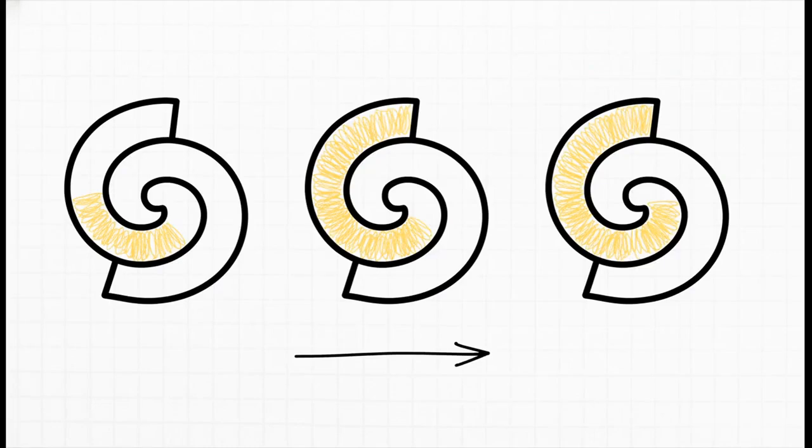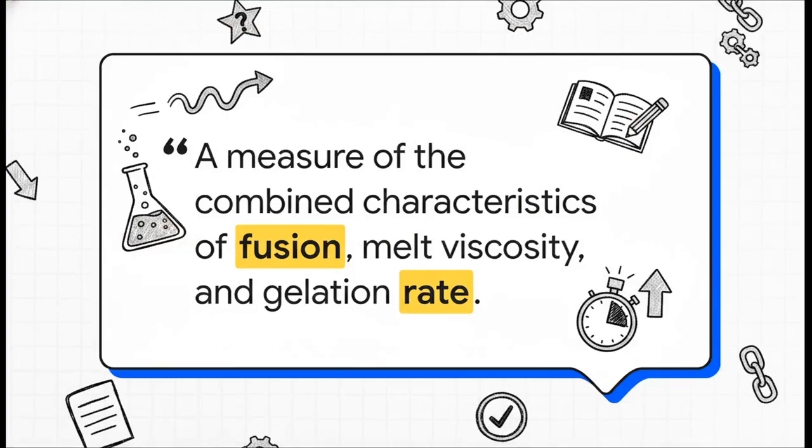Interpreting the result is a direct inverse relationship. Make absolutely sure this is in your answer. A higher spiral flow length means the material had a lower viscosity and much better flow behavior before it cured. Industry actually classifies compounds based on this exact test. Low plasticity is a length of 1 to 10, medium is 11 to 22, and high plasticity is 23 to 40. Here is your GTU tag. Write this down. This appeared as a 3- and 4-mark question in multiple papers, including the most recent mid-sem paper. It is the perfect, concise process question, so have those steps memorized.